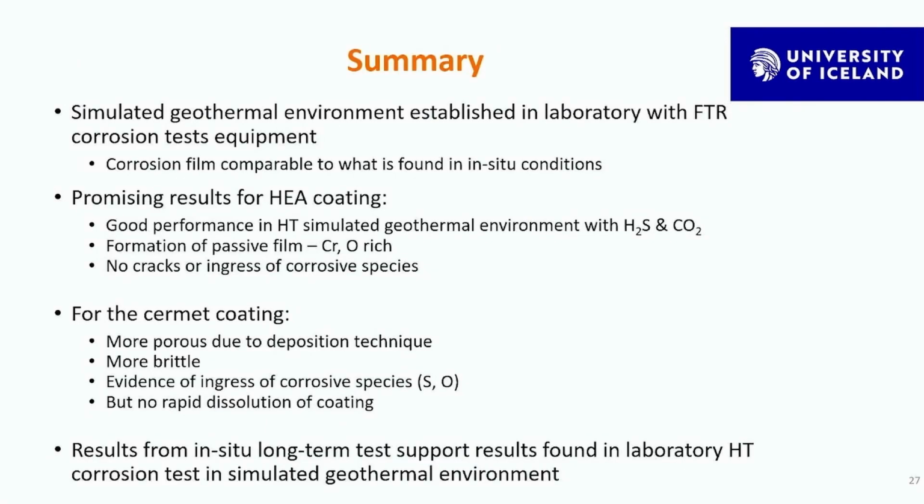So in summary, of the two most potential coatings for the rotor steel, the high entropy alloy coating was performing better in our simulated high temperature geothermal environment, and the cermet coating had evidence of some ingress and was also more porous due to the deposition technique.